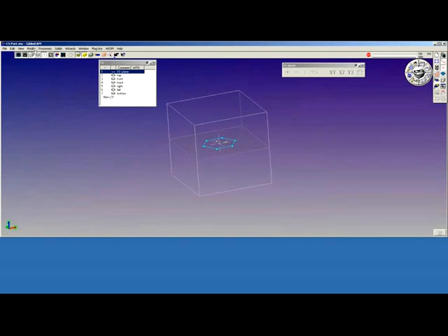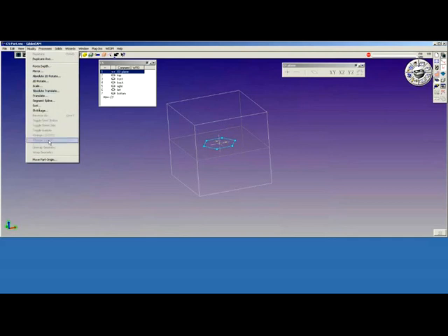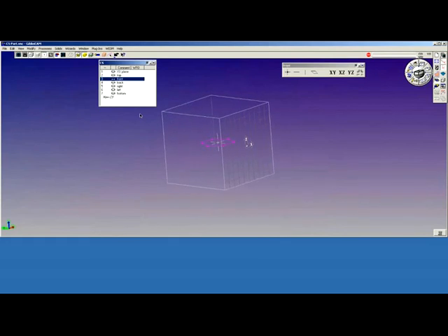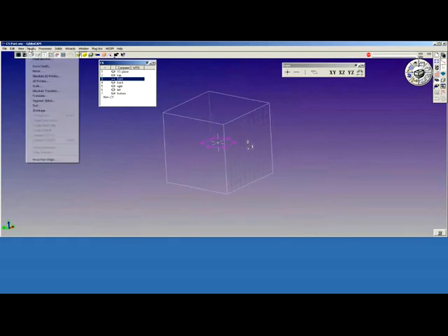The other choice, change CS HVD, and you notice that they're grayed out until you select geometry. Change CS HVD will move the geometry into another coordinate system. I go to my front coordinate system this time. Now, the two choices are change CS XYZ, change CS HVD.